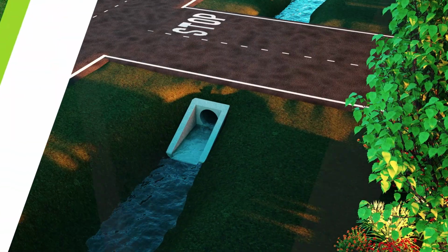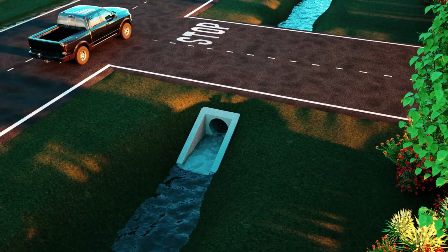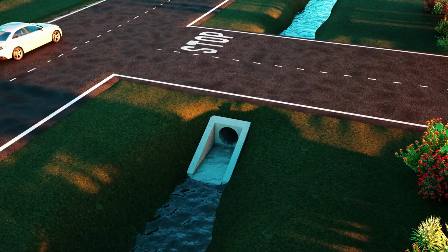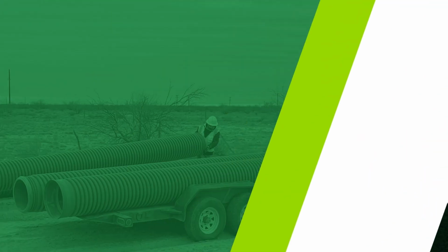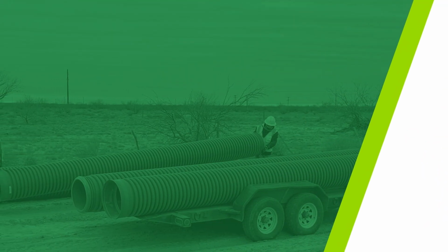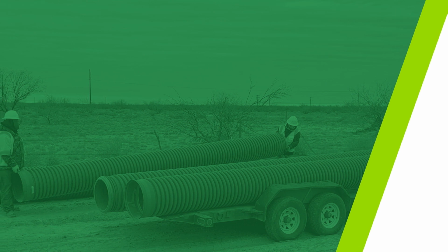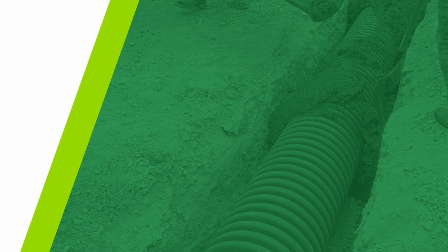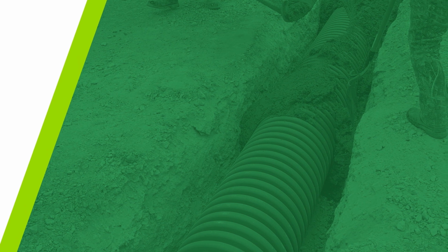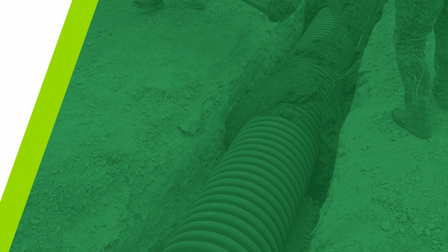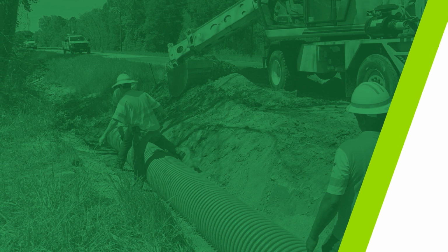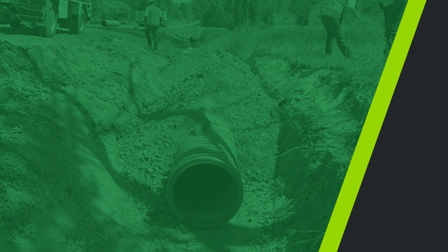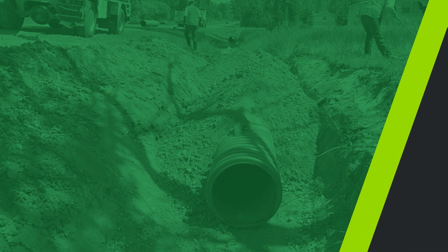The nation's growth and prosperity depends on a sound infrastructure. Culverts not only control erosion and ensure proper drainage, they ensure the long-term success of our roadways. ADS polypropylene pipe has longer spans, which result in 60% fewer joints, significantly decreasing the likelihood of leakage and surface failure. Additionally, polypropylene pipe is lightweight, which allows for smaller equipment and crew sizes, and a reduced number of trucks to and from the job site. These factors help reduce installation days and, more importantly, allow for a safer job site.